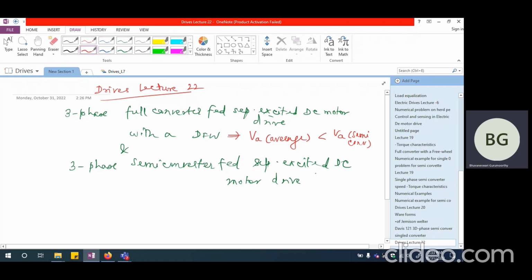So whatever is the most negative voltage that will come up, whereas the positive side voltage is controlled in this particular case, the negative side voltage is not at all controlled. Whereas here, both positive and negative side voltages are controlled. And only if there is a negative excursion in the DC link voltage, that is going to be completely eliminated.